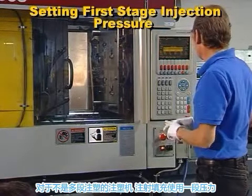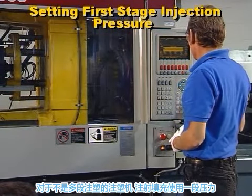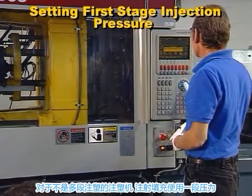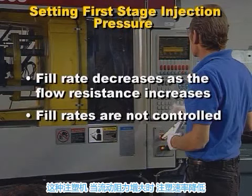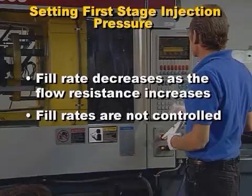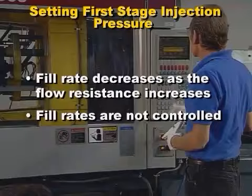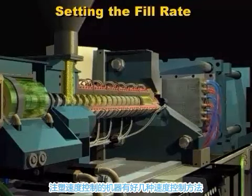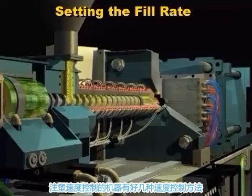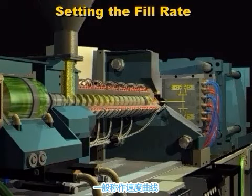On molding machines without fill rate control, mold filling and packing is done by using a single injection pressure, often called the first stage pressure. Because this is a single pressure, the fill rate decreases as the flow resistance increases. Therefore, fill rates are not controlled. Fill rate controlled machines have several fill rate settings. This control is commonly called boost, injection, or velocity profile.